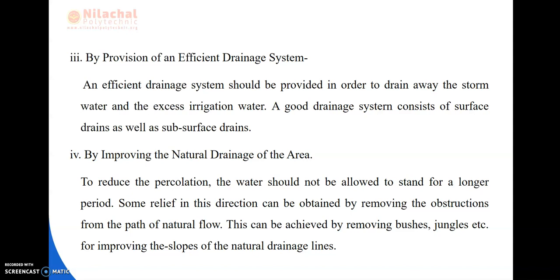Next, by improving the natural drainage of the area. To reduce the percolation, the water should not be allowed to stand for a longer period. Some relief in this direction can be obtained by removing the obstructions from the path of a natural flow.